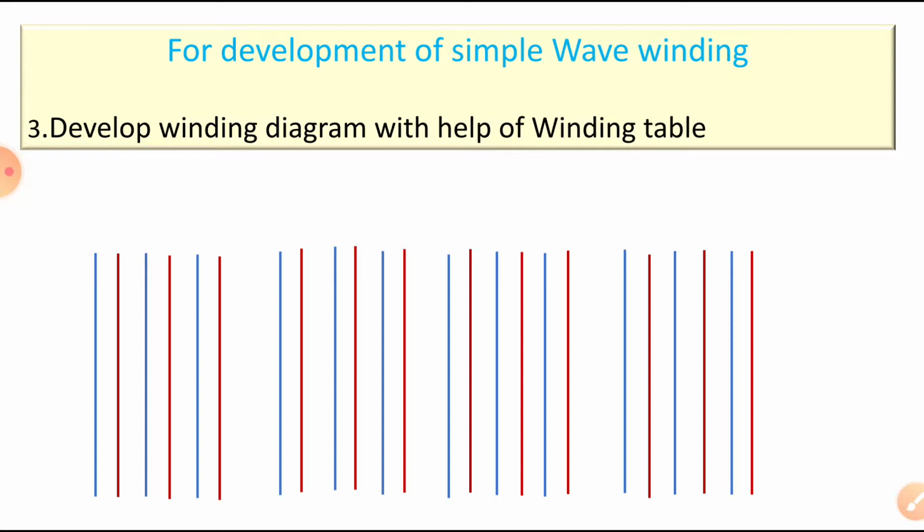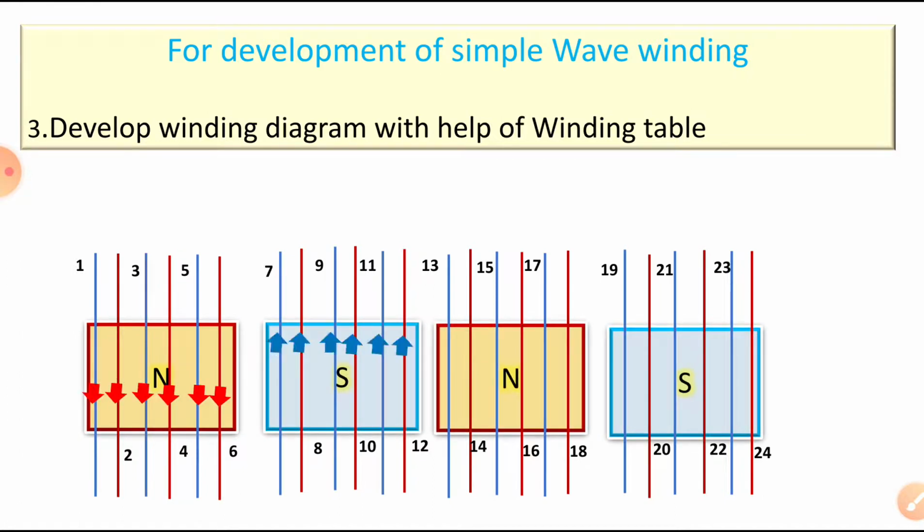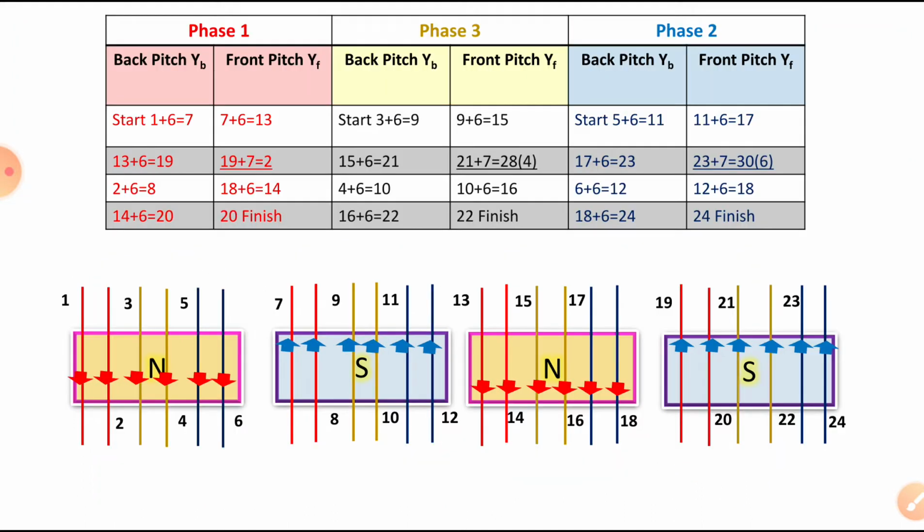Connect the coils as per this winding table and arbitrarily assume a particular current direction for the coil sides under the pole pairs. For the coil sides under the north pole region, assume a downwards current direction and vice versa for the south pole regions in the figure. Okay.